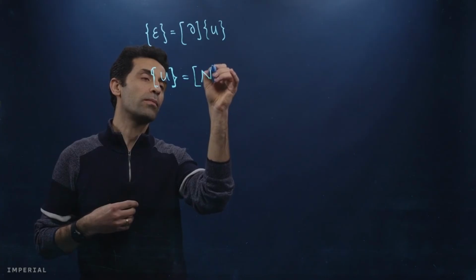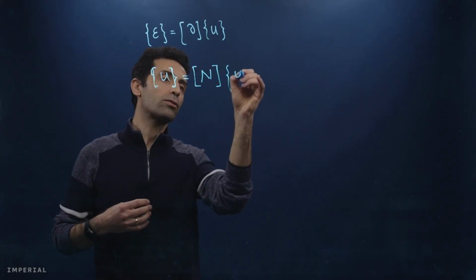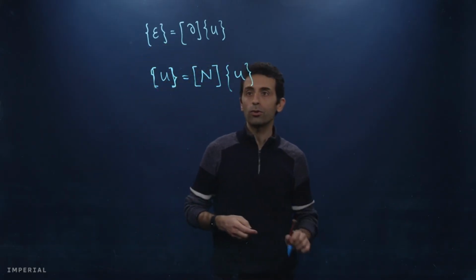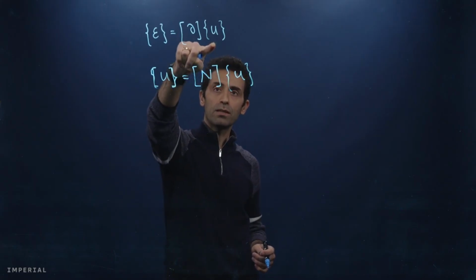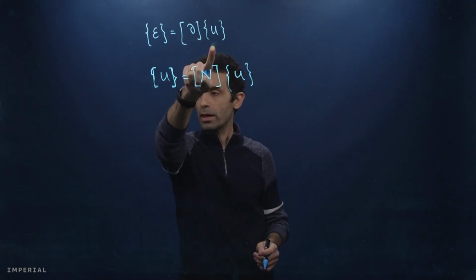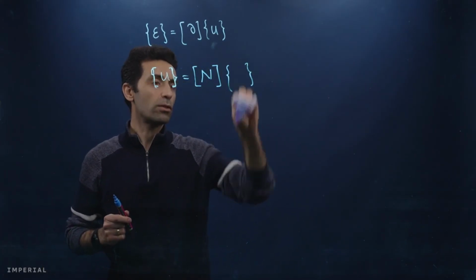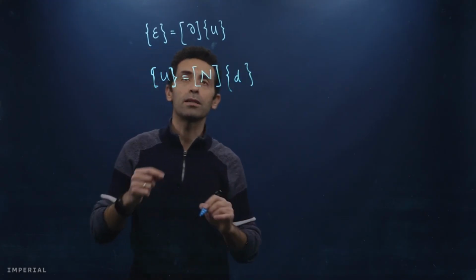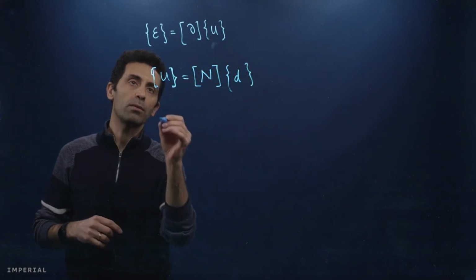So this is the tensor that includes all the shape functions, and here we have vector of nodal displacements. Okay, so you can see where I'm going with this. So now we can replace this u, this vector here. Here this is supposed to be d. So this is the vector of nodal displacement, which we always show with d, right? So now we replace u with this bit, and let's see where we go with that.